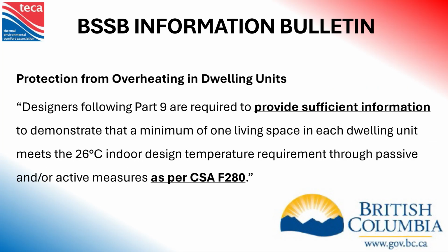Namely, in this sentence where it says, designers in Part 9 buildings are required to provide sufficient information to demonstrate that a minimum of one living space in each dwelling unit meets the 26-degree indoor design temperature requirement through passive and/or active measures as per CSA F280. But as we've just seen, there is no method for showing that a passive system is acceptable through CSA F280.